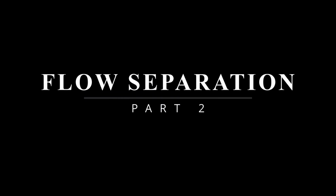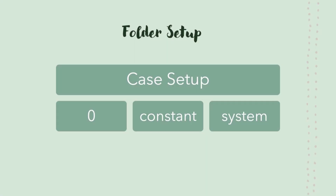Now let's understand the case setup for vortex shedding. One of the first things we need to understand about OpenFOAM is the folder setup. The case setup that you want to do for simulating any type of flow behavior requires you to place certain types of files inside each of these folders. There is a zero folder, there is a constant folder, and there is a system folder.